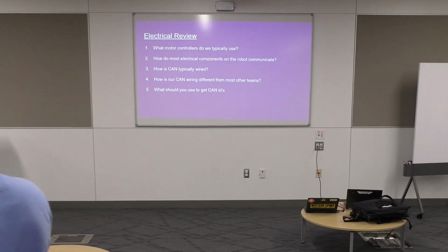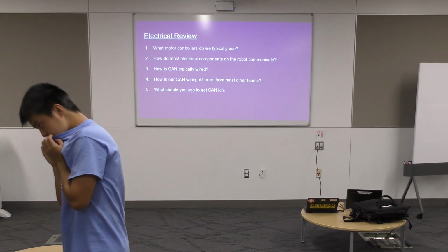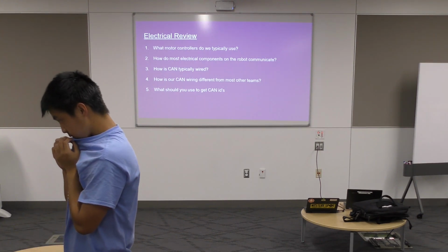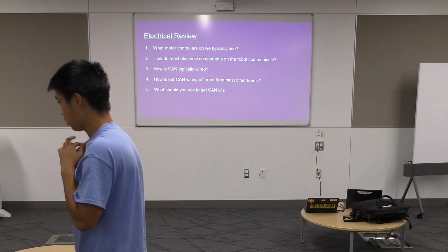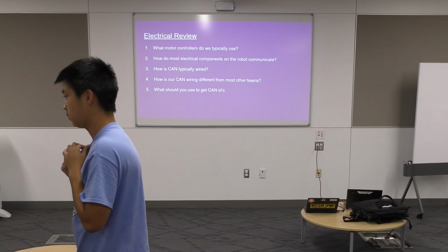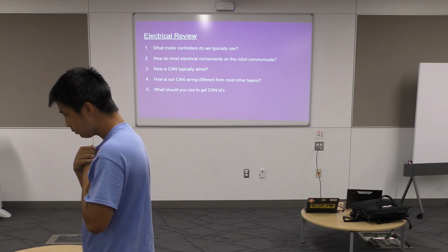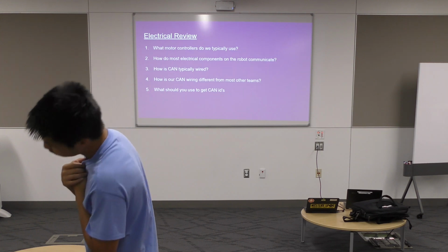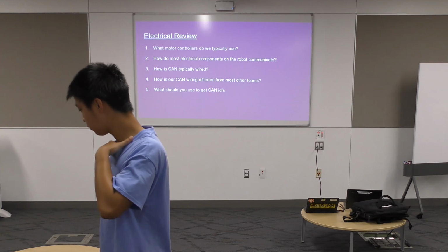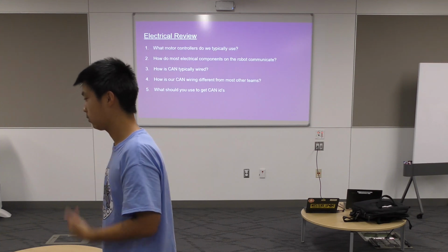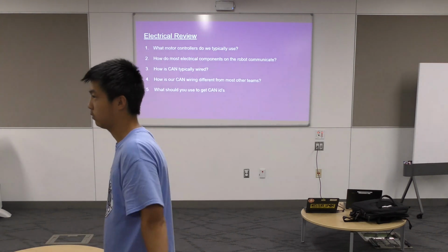One last thing, we're going to talk about this later. There are a lot of sensors on a robot. This one right here is the linear actuator, called the DART. It's controlled with something called a potentiometer. A potentiometer is an absolute encoder, which means it provides you a value based on a static point. Normally when you think of an encoder, you think of measuring how far you go. That's called a relative encoder.